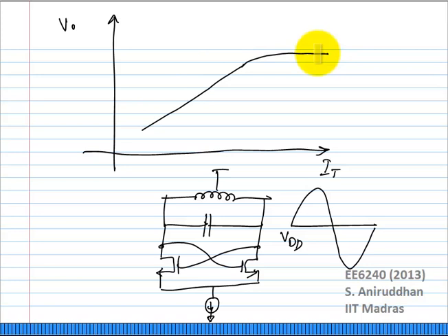Where else would you want to operate or not want to operate? Perfect. You want to maximize output amplitude for phase noise. Correct? How do you maximize output amplitude? There is an inherent variable here, RP, which we have not chosen yet. Right? So you can independently choose IT times RP also. Right? So, for any VCO, you want to maximize output amplitude, and as he mentioned, there are certain reasons why you don't want to operate on the far right side. So which is the best region to operate? In this knee region of the curve.